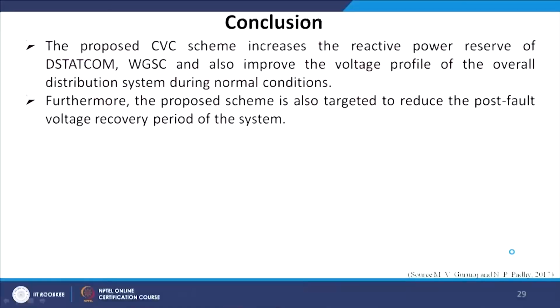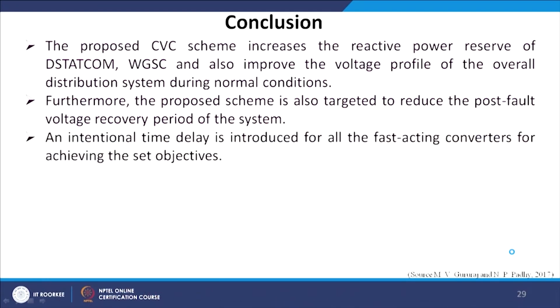Furthermore, the proposed scheme is also targeted to reduce the post-fault voltage recovery period of the system. An intentional time delay is introduced for all the fast acting converters for achieving the set of objectives.